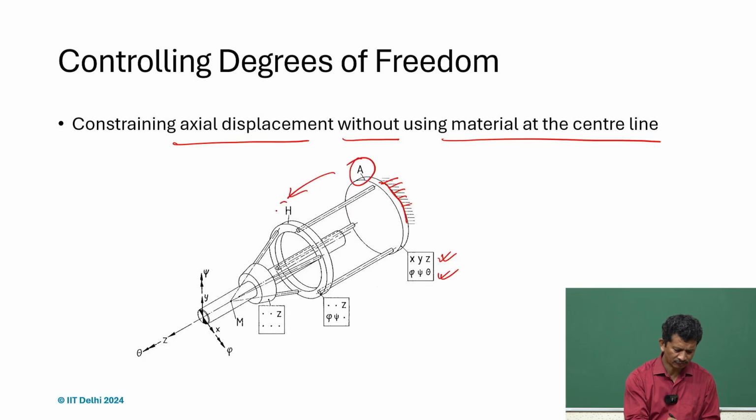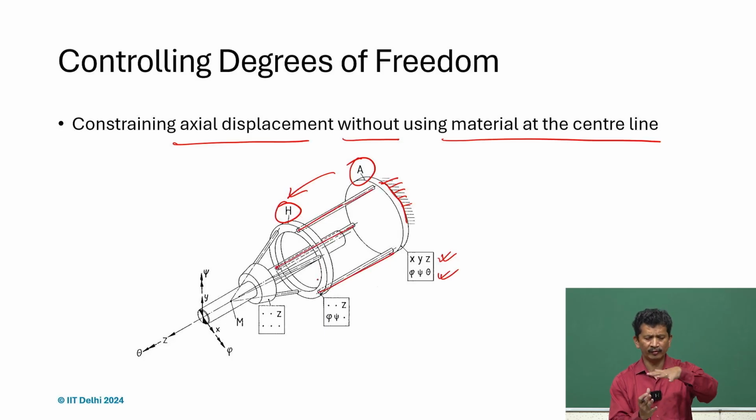Now, moving to H, the intermediate member. What we realize now is we use 3 linear constraints on the other side. And if we have this kind of a structure with the three linear constraints, what we get is it is constrained in a plane. So, it can only move in a plane. So, what we will have here is, this is the frame we are talking about, x, y, z. So, z will be constrained because it cannot go out of the plane, that plane defined by H, and the 2 out of plane rotations. So, these 3 are still constrained.